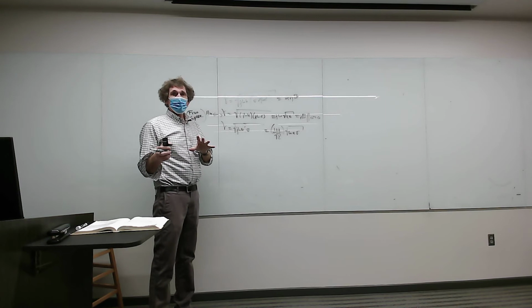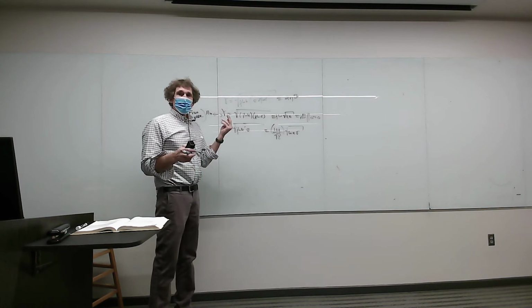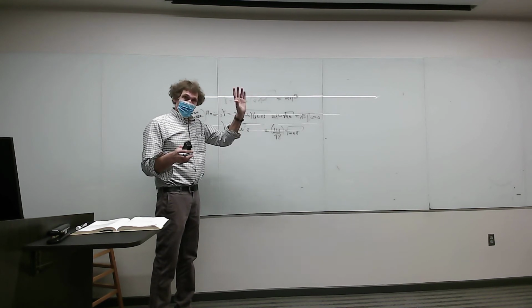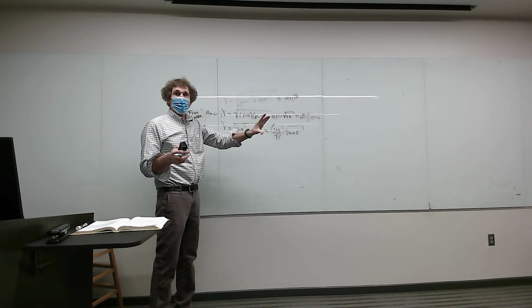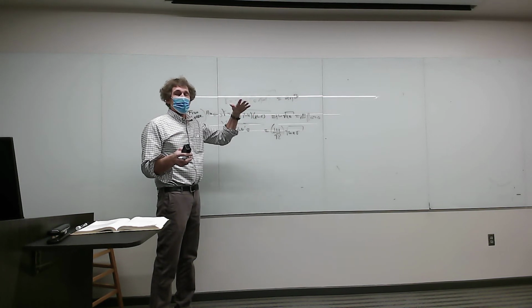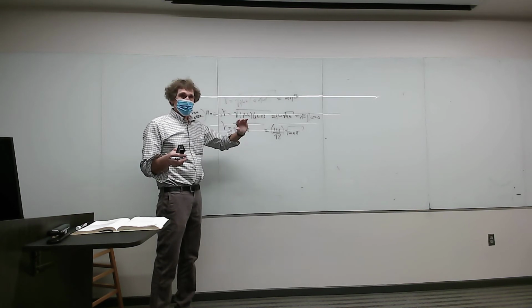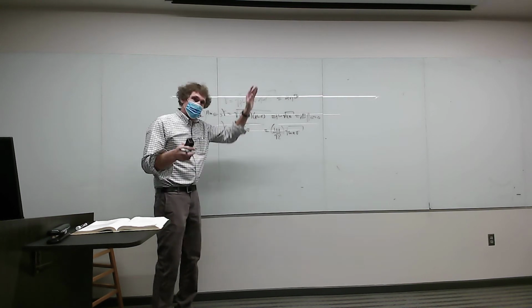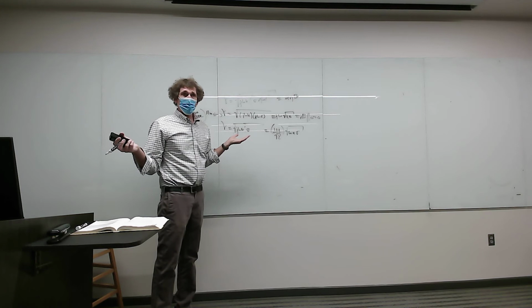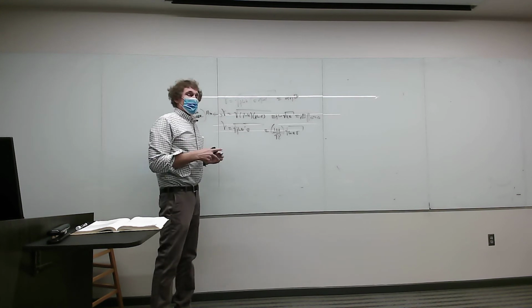Anyway, if you have those available, or if you're writing a program, like in a script file, I simply put in f, sigma, epsilon relative, and mu relative. I put all those at the front of the script. Right away I get omega, I get gamma, which is alpha plus j beta, I get the intrinsic impedance, the phase velocity, the wavelength, boom, I've got all the quantities. Now what do you want to know? It goes from there. Those will always be the same, no matter what. And that's the way I do it.